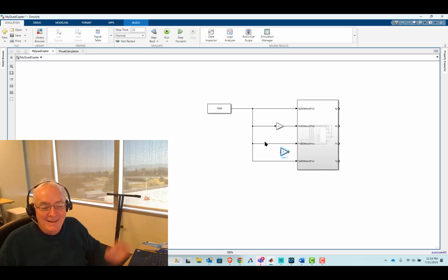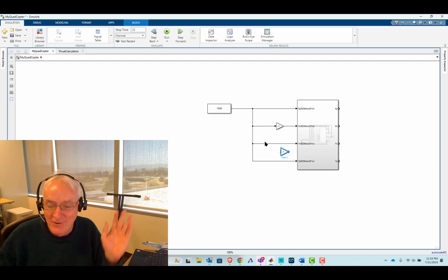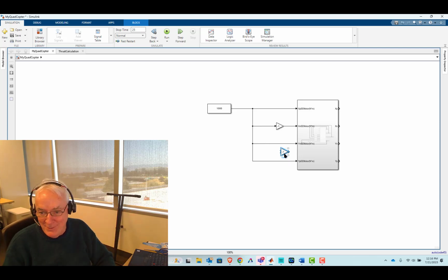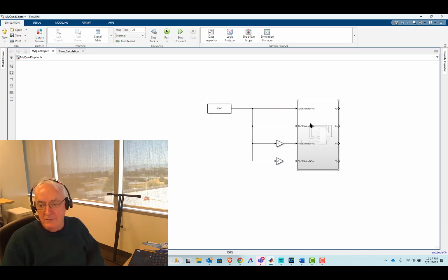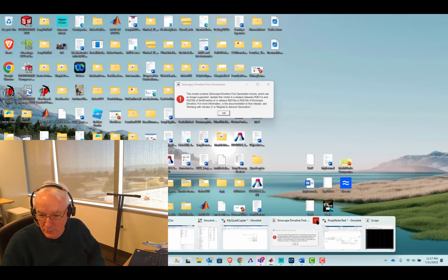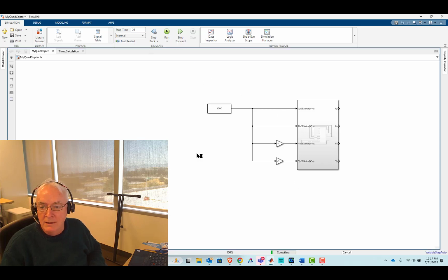It introduces an interdependency between the X and Y axes that would be very hard to deal with. I'm sure somebody super clever could figure out how to do it, but I'm not that person. So it's better to have them either on the X or the Y. In the video we just looked at, I put them on the Y, so let's be consistent with that. I'll move it there and delete that one. So X spins in the positive direction, Y spins in the negative direction. Seem fair? All right, let's hit run again.